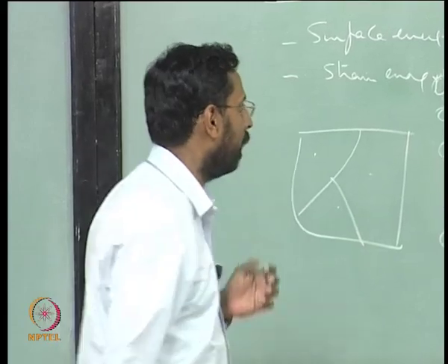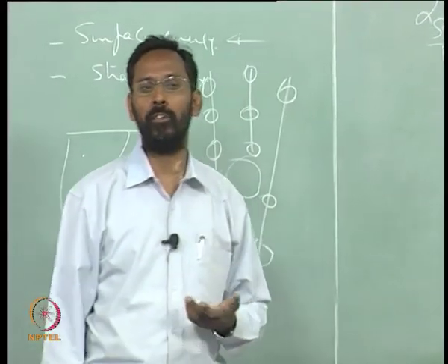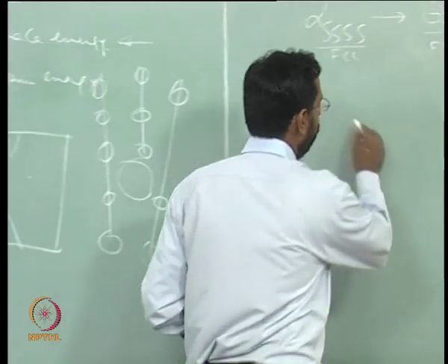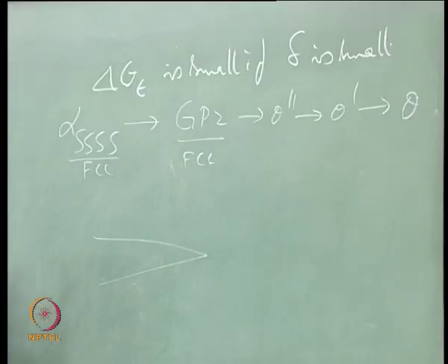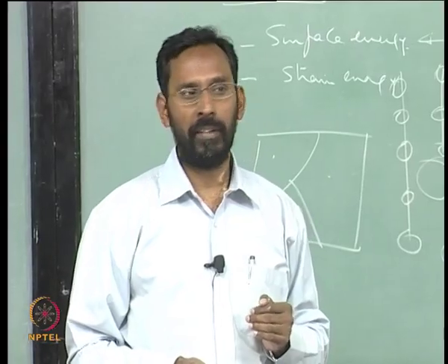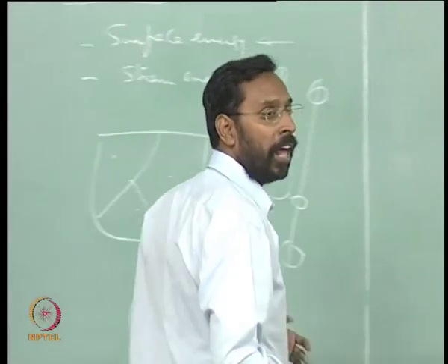Atom probe is a technique which is basically a field ion microscope, where you take a sample in the form of a tip and then basically sputter away the atoms. When you are sputtering away the atoms, the velocity of the atom is going to depend on the weight of the atom. This is what we call time of flight measurements.